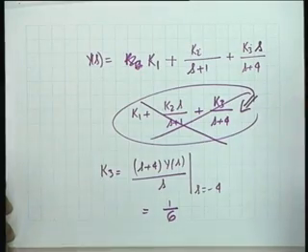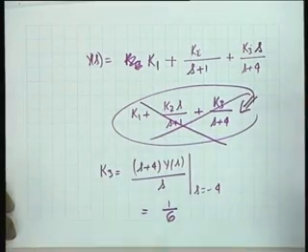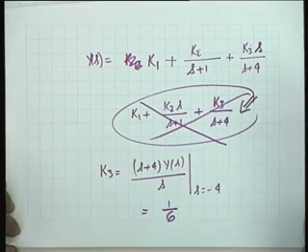I argue that one of the parallel combinations perhaps is RL. Which can it be? Obviously the one with a pole at s equal to minus 4. Why obviously? Because otherwise we found K3 to be negative. So how can we be sure about K1? Why should K1 be positive now? There is no guarantee. You have to find out K1.